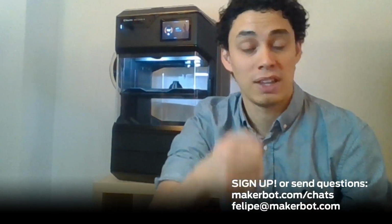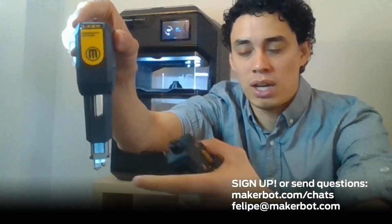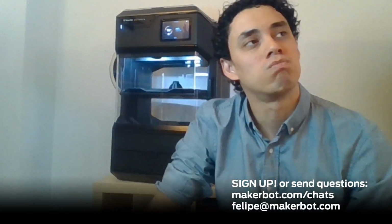So these new extruders are able to actually track filament jams, are able to have a longer heating distance, right? So that the material is, let's call it, happier as it extrudes. It takes a slower, longer melting process for the plastic to come out of the nozzle, which in turn makes the process itself very stable as a whole. So that would be the answer, right?